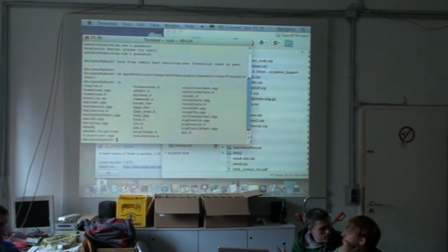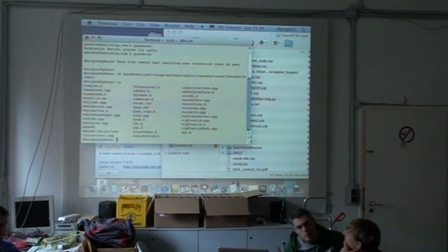But again, because of the computational demand, we don't do it all the time. We don't run them in parallel, we switch it on when we know an access burst is probably going to come. And once we've received and verified an access burst, we turn it off. So that's done the same way in other BTSs. That makes a lot of sense.